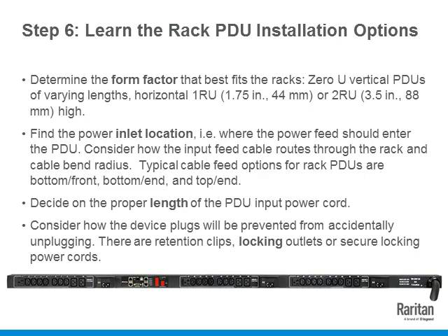The last consideration on the installation side would be the locking mechanism. How do you make sure the power cords from your servers or switches that go into these power strips stay there? They remain with all the movements happening around it, all the vibrations happening at the rack level because of all these spinning drives and fans in these devices. How do you make sure these cords don't fall out? We have several locking options where the outlets could be specially designed for locking any power cord, or you can have a specially designed power cord that could lock, or the good old method of using retention clips to keep these in place.